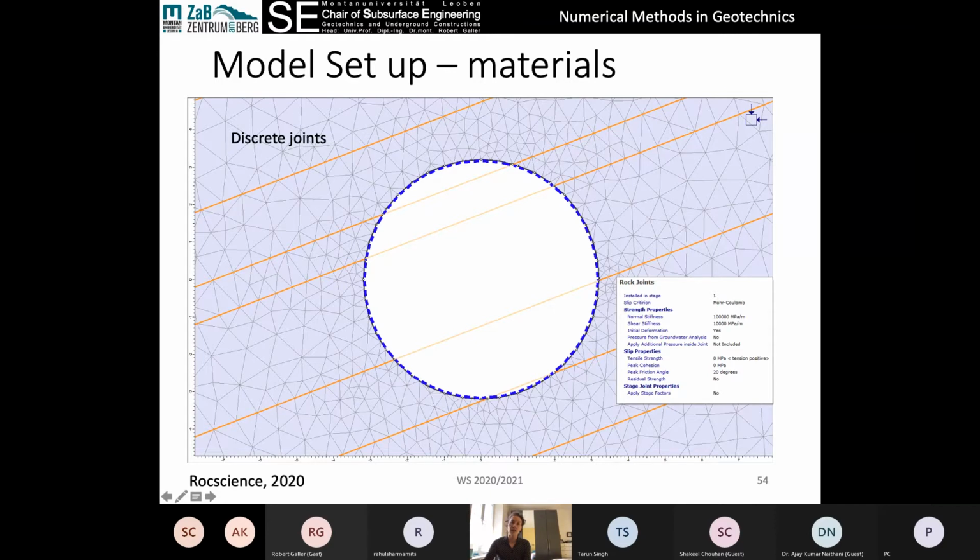And the level of detail then that we put to our geology depends on the scale of our model, the amount of detail that we're willing to compute for. So do we want to have very thin interbeds of siltstone in our sandstone here? Is that important? Is that an important component of the behavior that we think is going to happen? If so, then we should include them. If not, then we can sort of make an average continuum sandstone with siltstone interbeds, and we have to choose then how to represent that as Mohr-Coulomb or Hoek-Brown material. What sort of strength parameters do we put into there? And we then have to decide, do we want to use a Mohr-Coulomb or a Hoek-Brown failure criterion?